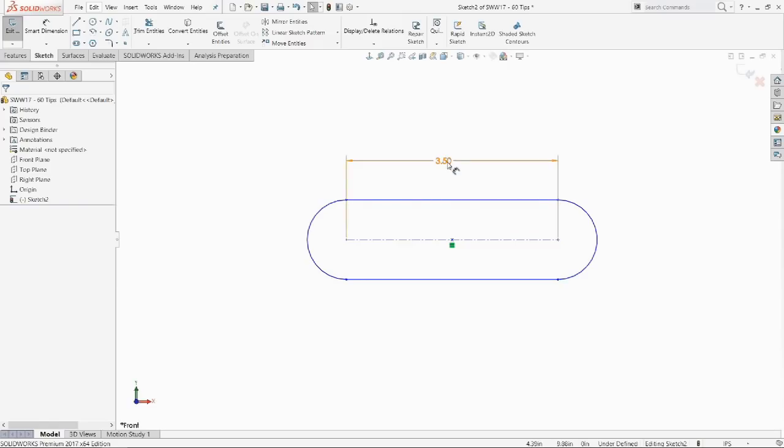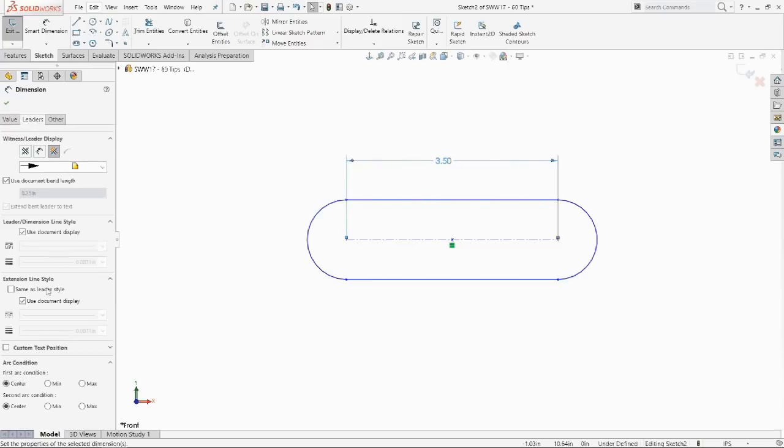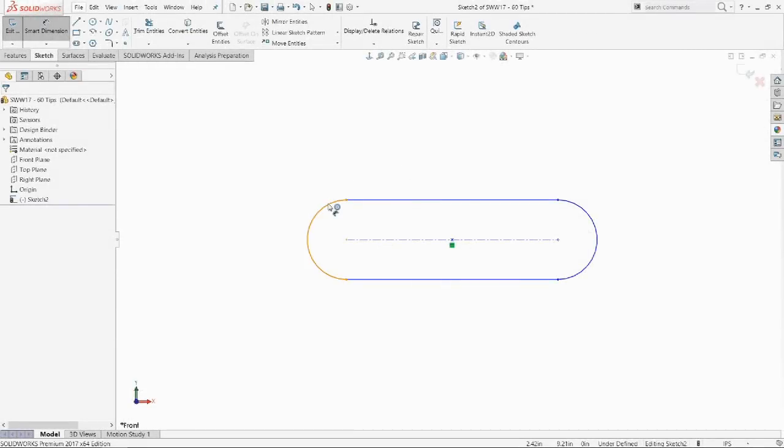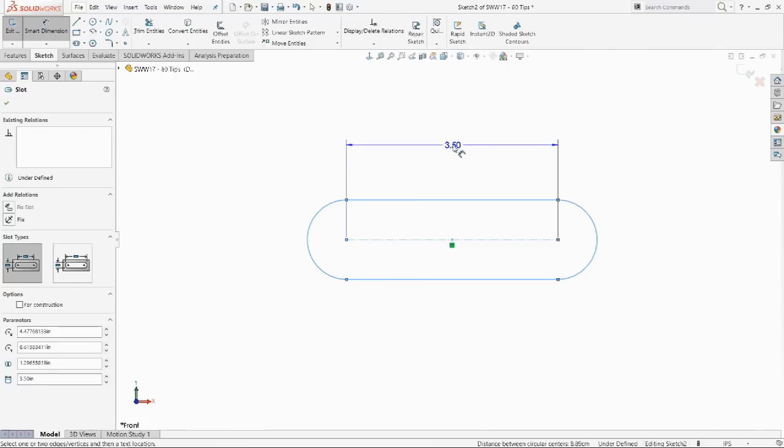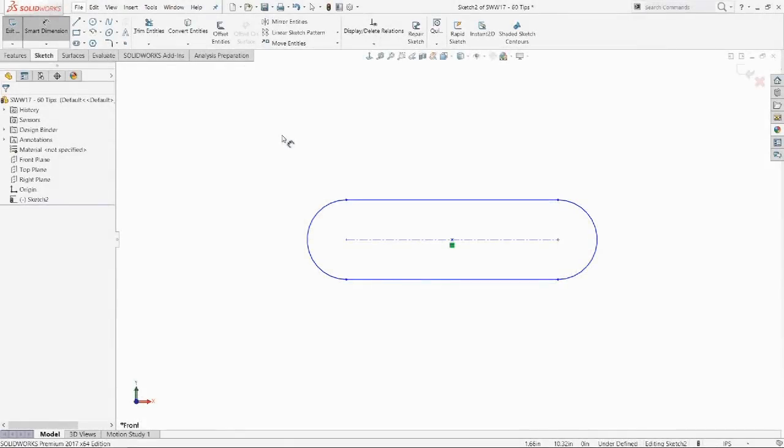But I'll point this out here in the first part of this video. When you click on it, you can go to leaders and then come down to the bottom and just change that way too. So you don't have to remember the fancy shift key. So you can go specifically between the arcs. Say arc 1 is going to be the center, arc 2 is the middle, or the minimum, or the maximum, right? So go ahead and start changing that.